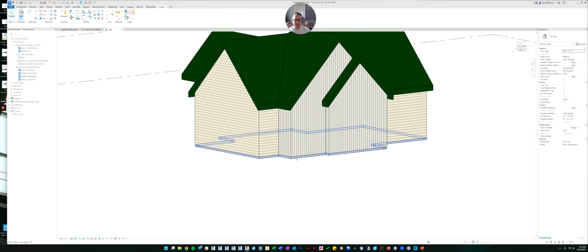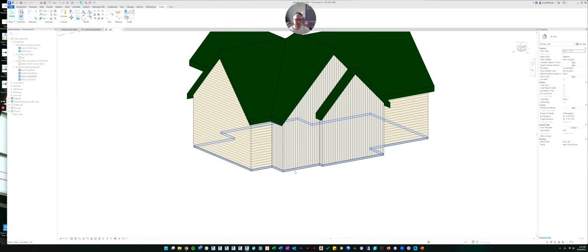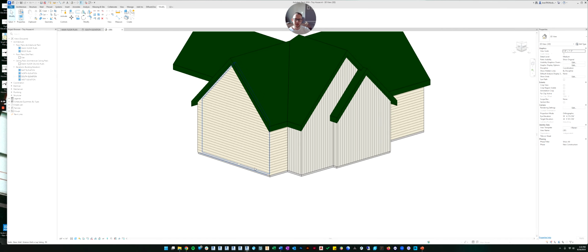Like before, we clicked a wall and then we edited it. We could click this floor and edit it, but we don't actually want to do that because the floor we put in is right. A 4-inch concrete slab is correct. What we want to do is maybe put in finished floors. So on top of the concrete slab, maybe we want tile or carpet. So let's look at how we would do that.